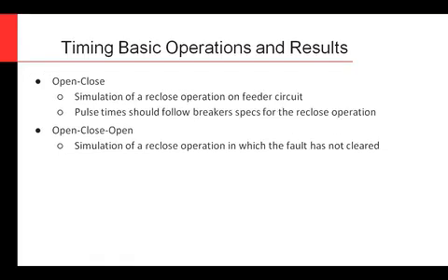But if you really want to be thorough, you want to go ahead and do your reclose operation, where maybe the real-world conditions, a lightning strike hits the line, the breaker trips, clears the fault, closes back in, fault's gone, no problem. One thing to pay attention to here is you want to make sure your pulse times are long enough and that your reclose timer is set long enough so you don't do damage to the breaker.